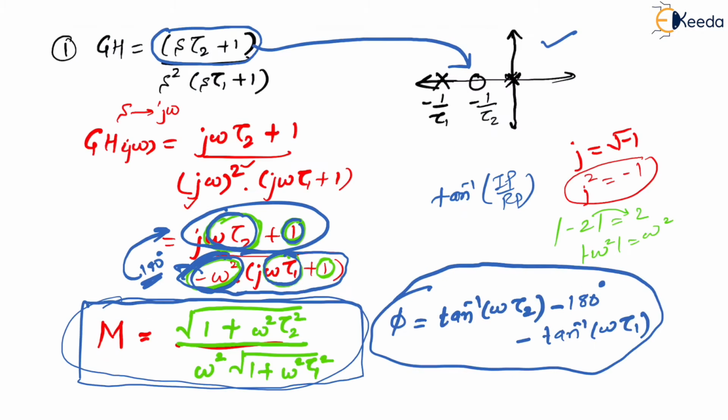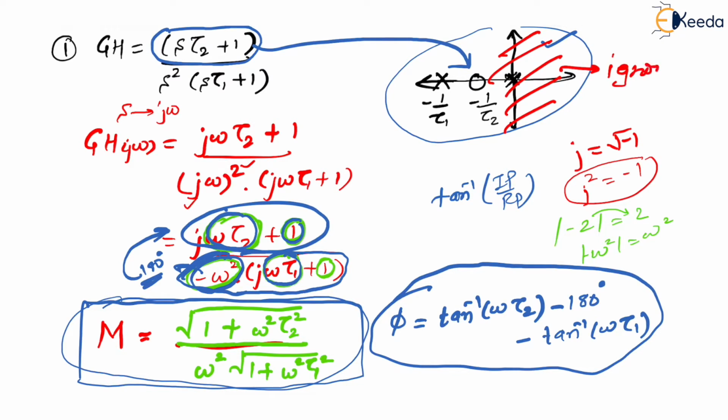If you think of step 4, step 4 gives you the starting direction, right? And if you observe, this is the pole 0 plot. In that pole 0 plot, what did I say there? I had told you already that whatever is there on the imaginary axis as well as on the right half, you have to ignore. So you have ignored it, right? Now you have to only think of what is there on the left half of S plane.